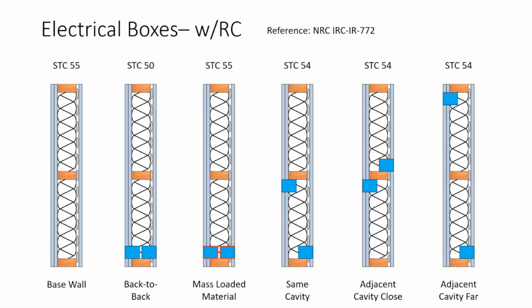So there's a bunch of different ways that you can do this, but carefully specifying exactly where your electrical outlets are going to go on a job seems like an awful lot of detailing, and there's just chances that things are going to get moved around. So I think just requiring a putty pad or something like that is a good way to put into your specifications. And also oftentimes a fire putty pad may be required in a fire rated wall anyways. So it can do double duty. And oftentimes our acoustical separating walls are also fire separating walls, especially for multifamily construction.